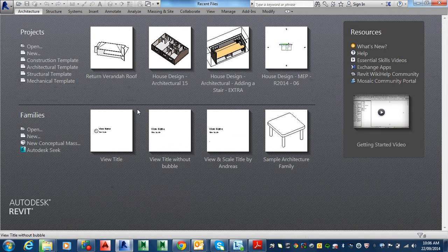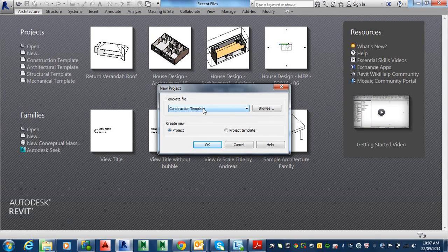Okay, we'll begin having a bit of a look at the Autodesk Revit user interface. Generally you're faced with something like this when you first come in, and your previous projects will be sitting here; yours will be different. We'll head over to New here, and you've got 4 different templates. We'll begin with the architectural one because that's the house we're going to end up drawing. And of course there's no surveying one there, or not yet anyway. So let's go to OK then.